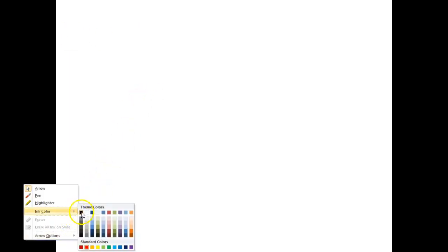So we come up here, I've got a resistor, then I have a capacitor. And it's a polarized capacitor, so I have it like that. Then I'm going to put a 5-volt DC source here. I have to make sure I honor the polarity on my capacitor, even though, guys, this wouldn't hurt it because we're protecting it with a 100K ohm resistor. It's just that you would actually see it not charged, and you'd see current flow through it.